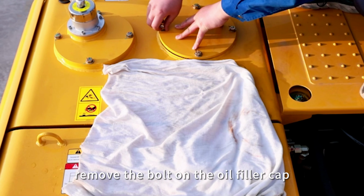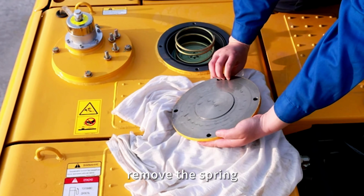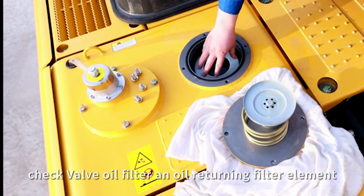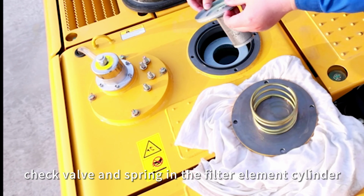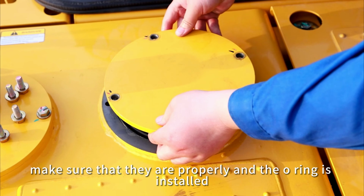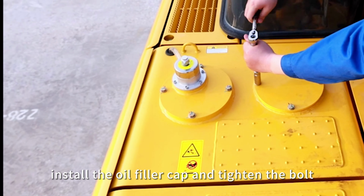2. Remove the bolt on the oil filler cap, and remove the oil filler cap. 3. Remove the spring, check valve, oil filter, and oil returning filter element. 4. Install the new oil returning filter element, oil filter, check valve, and spring in the filter element cylinder. Make sure that they are properly installed and the O-ring is installed.